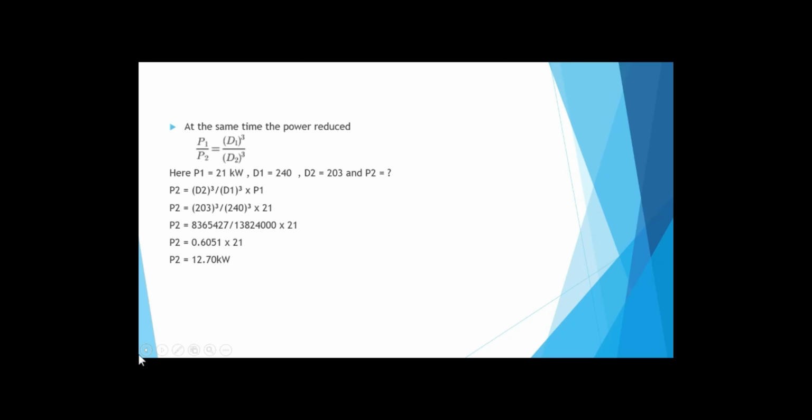So the affinity laws are helpful to trim the impellers at site to suit the actual site conditions, because the motor draws more current than stated by the pump manufacturer. The reason being the actual operating head is much lower than estimated. Thus the pump operates at excessive flow. Sometimes at actual site, a flooded suction is available instead of the suction specified.